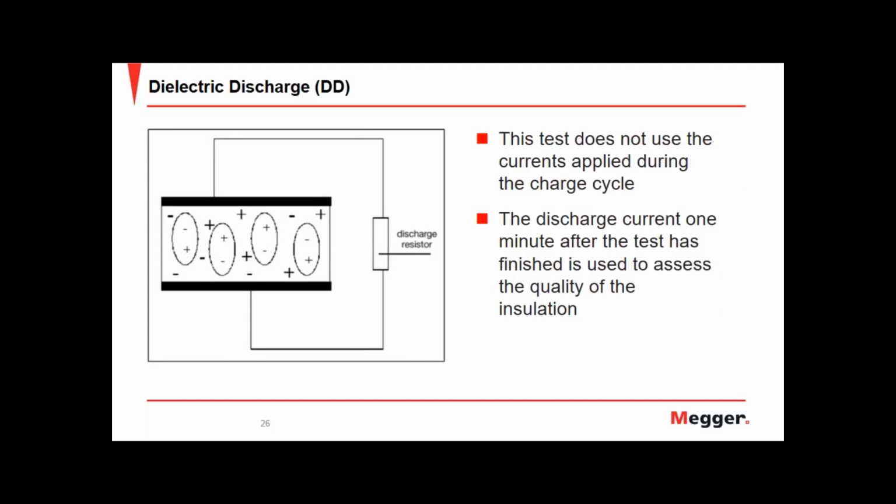Okay, the dielectric discharge test. This test differs from other time tests as it does not measure the currents during the charge cycle. It measures them on the discharge cycle. It was designed by EDF in France because it can reveal the condition of an insulation system as opposed to an individual insulation material.